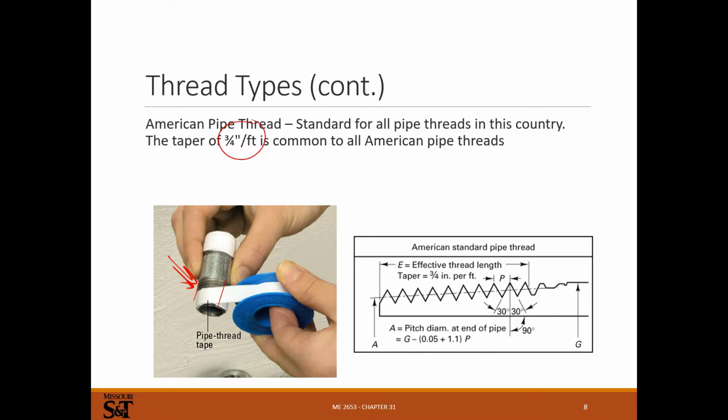You usually need some kind of lubrication to get the threads to engage enough to seal, and that's what this Teflon tape is all about. So you really only need Teflon tape on tapered threads. There's a few other applications where you might want it, but straight threads, it doesn't really do anything. It's usually not the seal on straight threads. On these, this is the sealing portion. It seals on this plug, so you really need that to be tightened a lot. In that case, you need something to lubricate it. That's what the Teflon tape does.